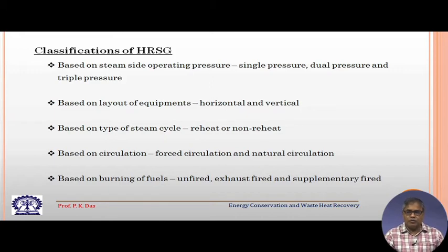The second one which one can think of is that combustion is not complete in the combustion chamber. The hot gas which is coming might have some amount of fuel left in it. So, a second round of combustion without adding any additional fuel in the HRSG, after the gas has come out of the gas turbine, is possible, and this is called exhaust fired. This is not very common, but this is an option.